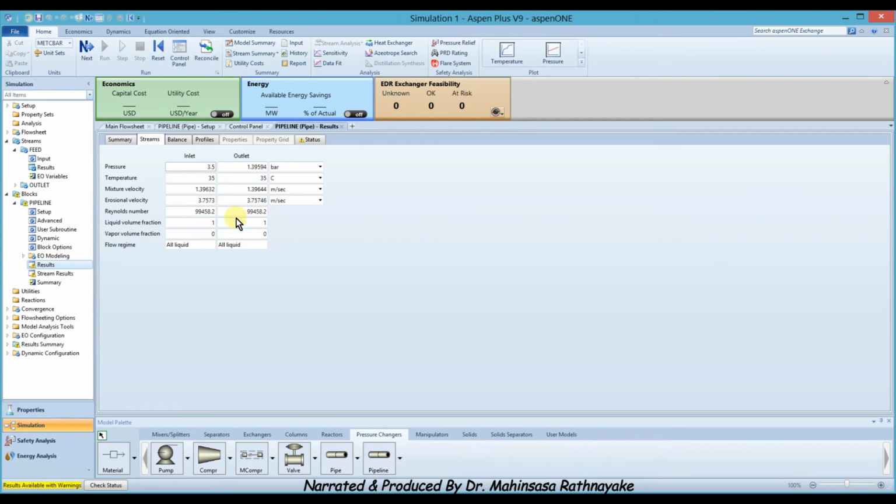And also we can see that the pipe outlet pressure is more than 1.2 bar, which is the outlet pressure in the CO2 capture system, so that we can conclude this simulation is correct. Next, we will discuss how to add a pump to this system.